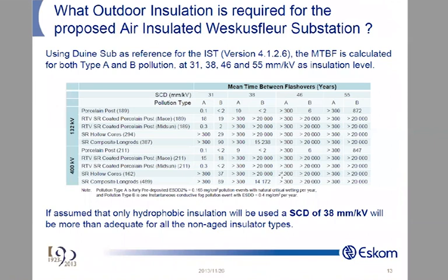But every product has got its usage. You need to just understand the material. You need to understand the insulator you're working with. And there are pros and cons in all of them. You can use an EPDM, for instance. You just compensate for certain aspects, which means the area is going to increase. So you need to go for a longer creepage. So you need to increase L. You see again, rho L over A.